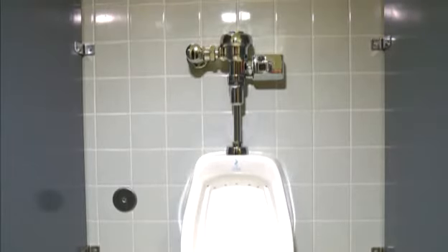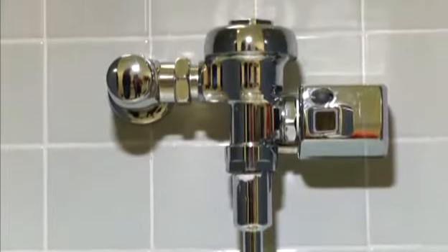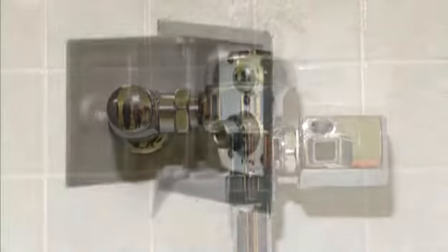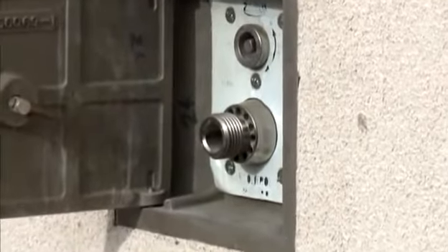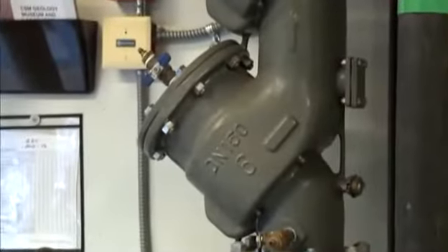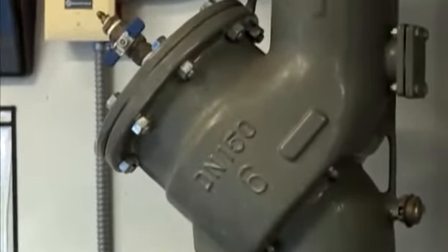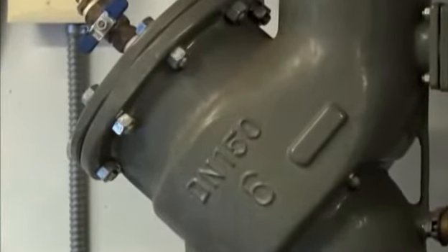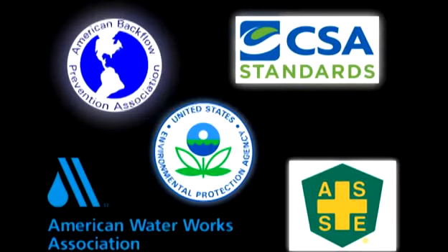Properly selecting a backflow preventer depends on an accurate assessment of the risk of contamination of a potable water supply. The degree of hazard, high to low, must also be identified. Installation criteria and hydraulic conditions must be evaluated by a trained professional before a backflow preventer can be installed. Several organizations set and recommend certain types of methodologies, devices, and assemblies of backflow preventers.